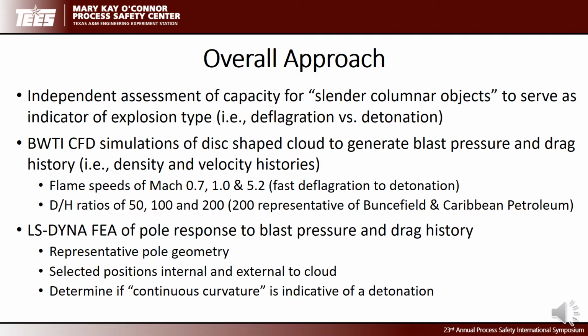And based on those blast pressure and drag load, density and velocity histories, we did finite element analysis using the LS-DYNA code to look at the response of poles to both the blast pressure and drag history combined. We picked a representative pole geometry and we looked at selected locations both inside and outside of the cloud. And again, our goal here was to determine is continuous curvature indicative of a detonation or not.